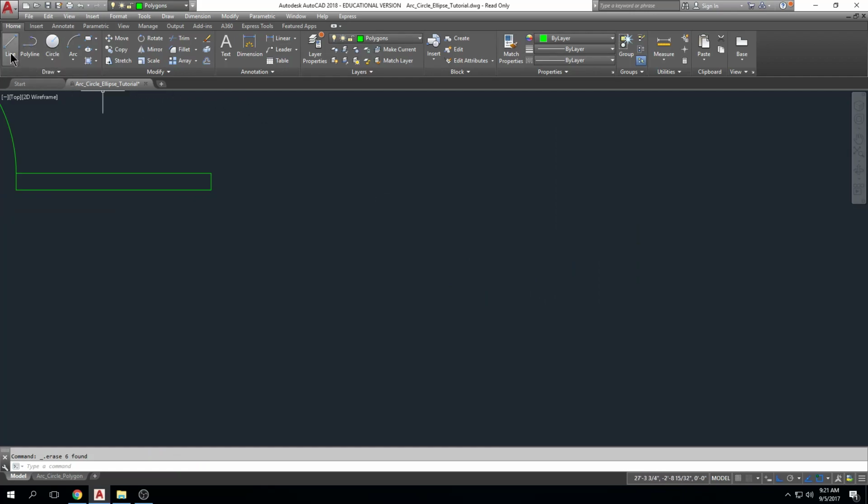I draw my first object, and I'm going to offset it. Let's say I want to offset it 2 inches. Offsetting will allow me to create a copy of one object a specific distance from the first object. So I come up here to offset, click. It's going to ask me to specify my offset distance. Let's type in 2 inches, enter. Select the object to offset. This is it. Click, click, click, click.